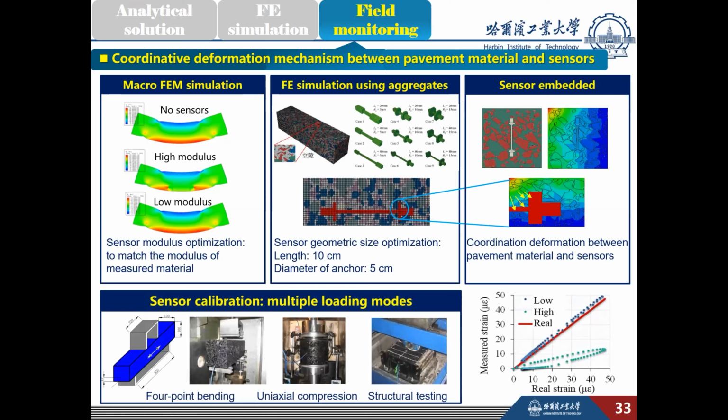In addition, we developed 3 calibration tests under different loading modes, including the 4-point bending beam test, uniaxial compression test, and the structural testing adapted from the wheel tracking test. In this way, we could validate the working performance of the developed sensors.